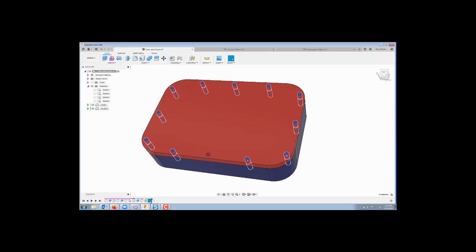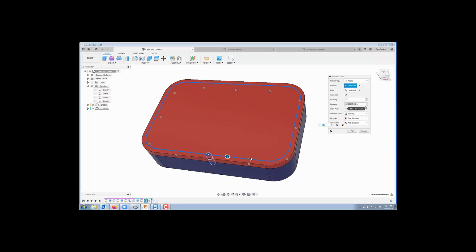All right, and I can actually, even if I edit this, all right, and what that number is going to be, because I have it all figured out here, if I go to extents now, here it is. This would be the 26.2832 minus that 2.1903. This is what I come up with. This is from this hole all the way around, ending at this hole, the last 12th hole. All right, and then it would equally space it on that length. 12 holes equally spaced over that distance. That's why I kind of like the spacing.